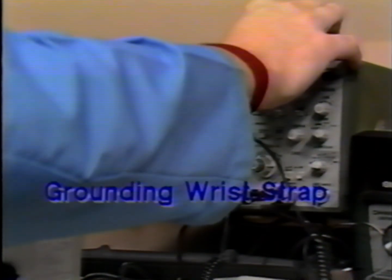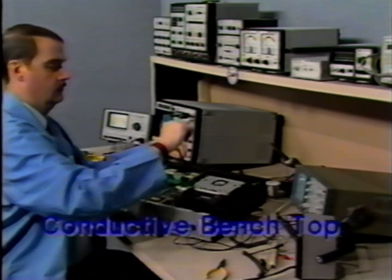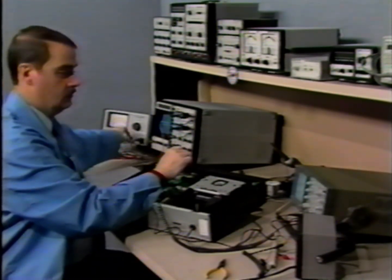The power supply voltages must be correct for the microprocessor to work properly, so the power supply test should always be the first performed, and any power supply problems must be repaired before troubleshooting can continue. When servicing microprocessor circuits, remember that most components are susceptible to damage from electrostatic discharge. Notice that we're using a grounding wrist strap and a bench with a conductive work surface. We recommend that you use these procedures as outlined in the accompanying reference booklet.